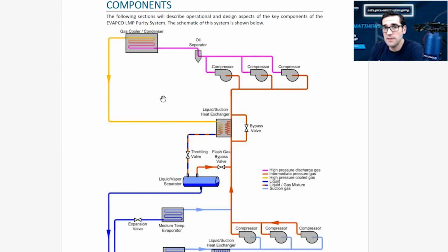This was a question I had: how come I see all these copper pipes coming out? I was told that copper at that time, I didn't even know there was such a thing as high pressure copper with the copper iron alloy in it. But I've seen it on there, but it had a stainless steel header. And this is what you need to know. As the pipes start to get bigger, the pressure rating starts to go down. And when the pressure rating goes down, that means you may not be able to use that specific pipe when you hit a certain section of pressure in your system.